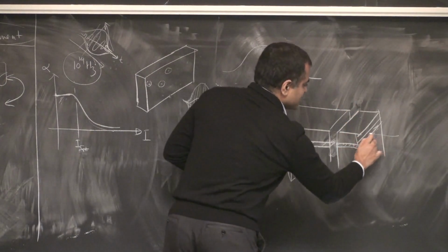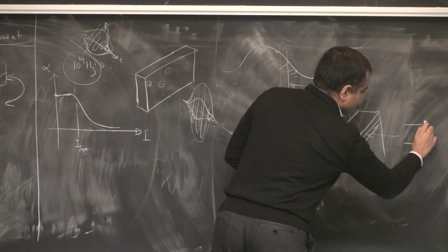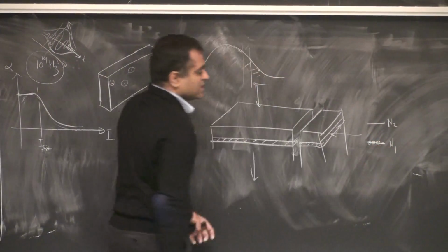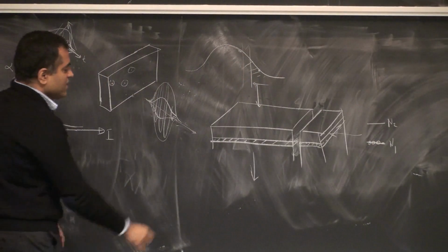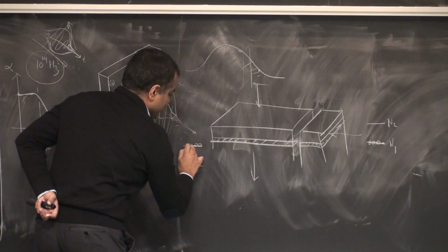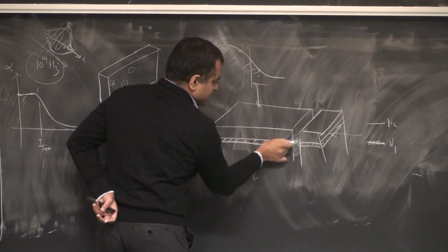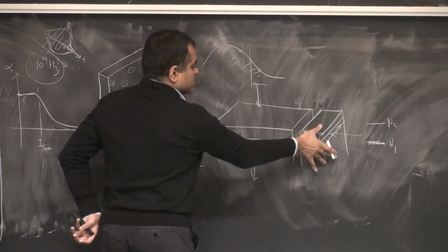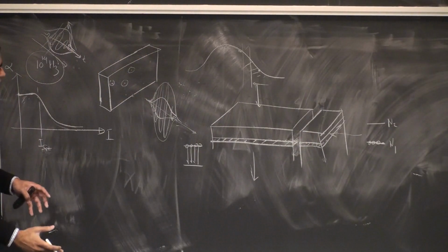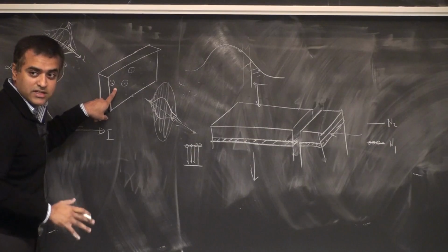Therefore, this region is sitting as a passive absorber, because since you're not injecting any current, you don't have any population inversion here. Whereas here we're injecting current, so in this region I have population inversion, getting stimulated emission and all that. The light is coming out here, and right next to it is a saturable absorber. It's sitting right there with no excitation, therefore it has no gain. In fact, it has a little bit of loss, but it's a saturable absorber. It can only absorb a certain density of photons.